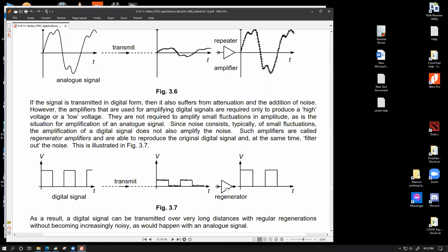But whenever it is picked up by the receiving end, we have a regenerator over here. What the regenerator does is it does not identically amplify this thing. The regenerator circuit or regenerator equipment observes the received signal and assigns its own voltage onto a signal.